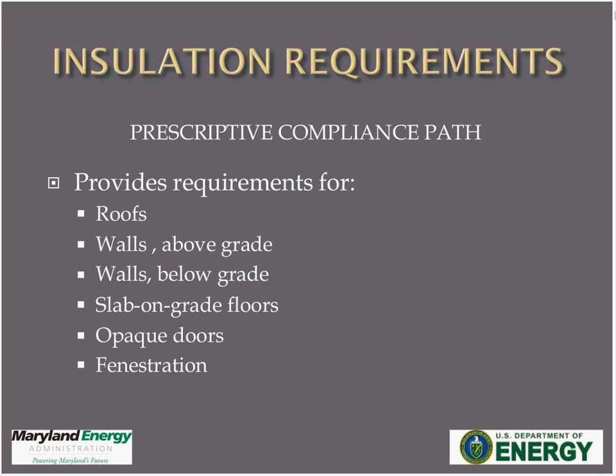Air sealing compliance requires a continuous thermal envelope as well as a continuous air barrier. The building envelope includes materials that enclose conditioned space or boundaries between unconditioned and conditioned space. Building best practices indicate that the insulation and air sealing systems should be as closely aligned as possible. Elements need to be present at the roof, walls both above and below grade, slab on grade, at openings and fenestration as well. C402.2 provides the thermal requirements of these items.